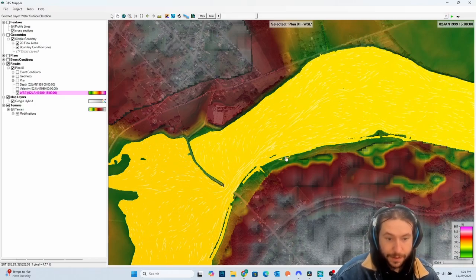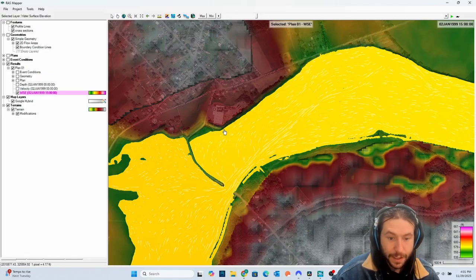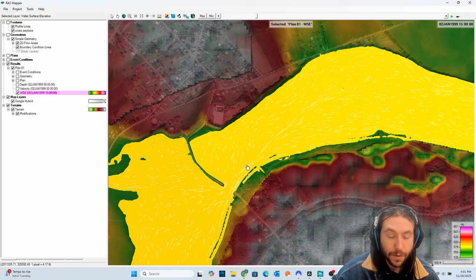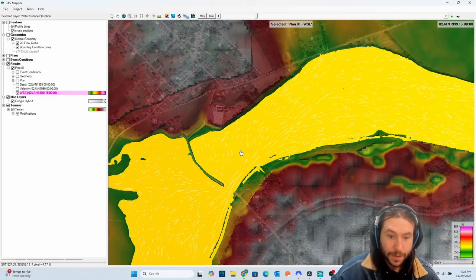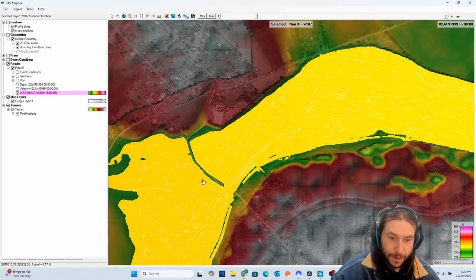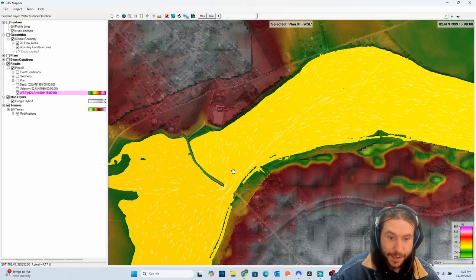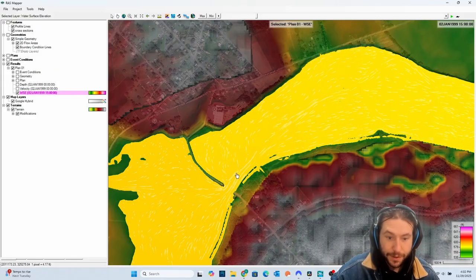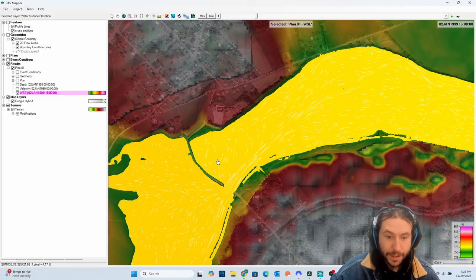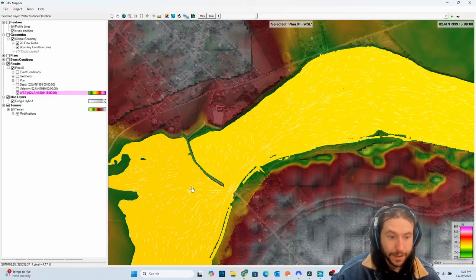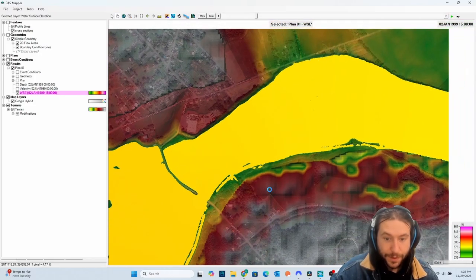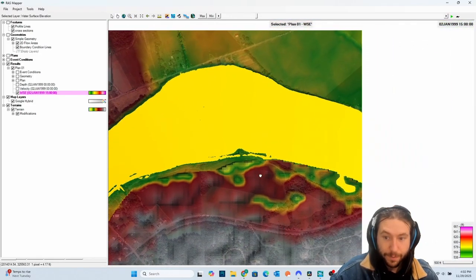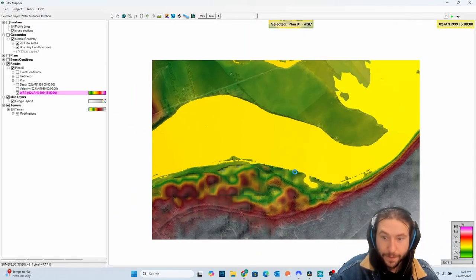And what the difference is, this doesn't use the, what do you call it, eddy equation. So there's no recirculating currents. This is just single direction currents, average currents going through here. So it does not calculate losses from eddy currents. We can turn that on, but again, it takes a lot longer to run. So for first initial equations, we just want to run our main equation here.